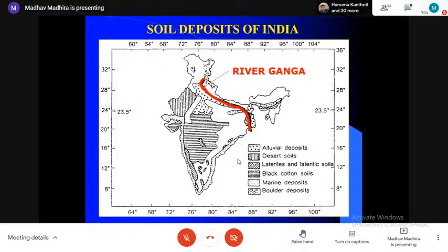If you start looking for the kind of material near Haridwar, it will land because by the time it crosses Rishikesh, the gravel is all deposited. So from coarse sand, by the time it comes to Aligarh, the Narora power plant, you get fine sand. By the time you come to Allahabad, Varanasi, it becomes a silt, clay silt or sandy silt. By the time we reach Patna, it becomes clay silt. And by the time you reach Howrah and Haldia, it becomes more of silty clay.